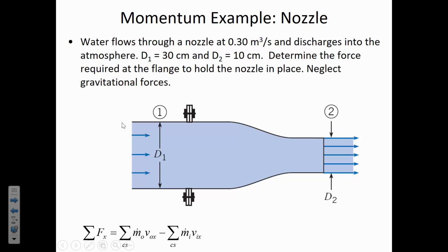It's not just a change in pressure that occurs, which is what Bernoulli's equation models, but the momentum equation is saying that we're going to have to apply some force to hold this system steady. But it's not just the external force that would be applied here at this flange to hold the system steady, because the pressure that's in the pipe is acting on whatever's inside of our control volume.